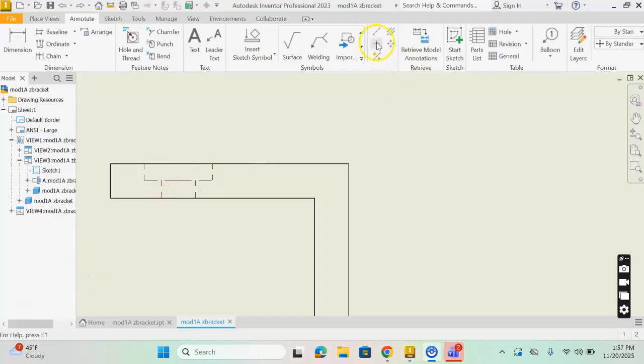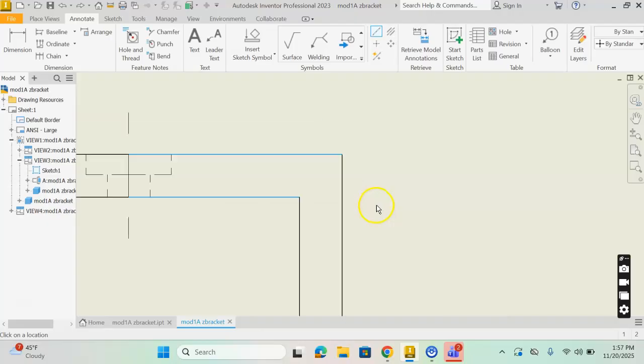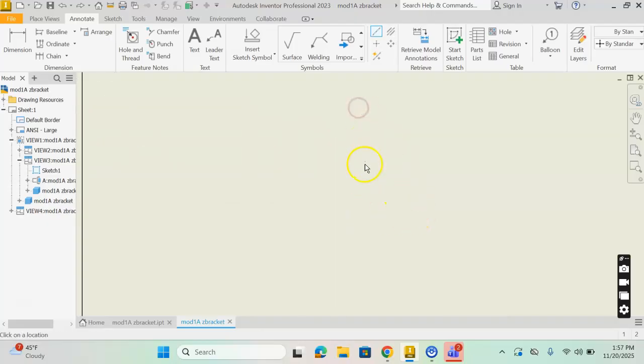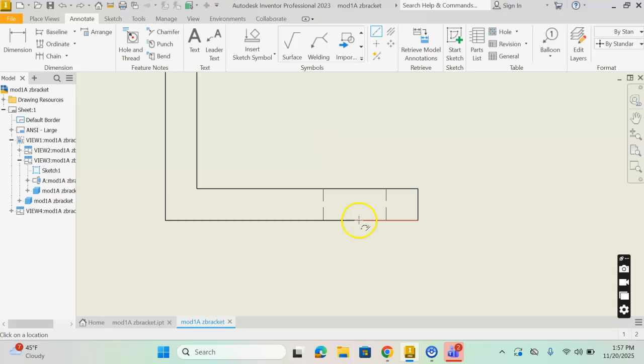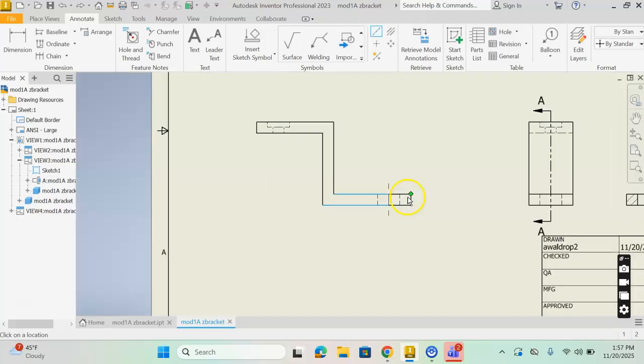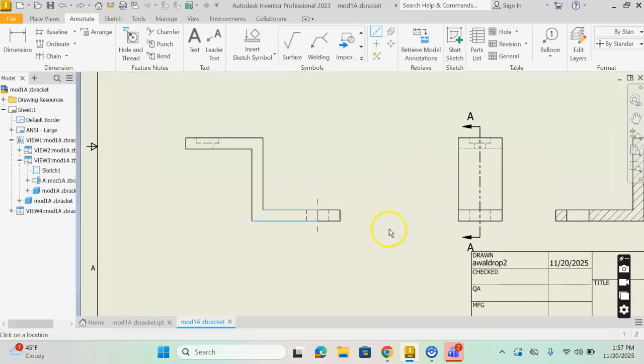So again, I got to click on the axis bar or the icon up here on the menu. Click the two areas that are going to form the center line. And once I click on that, it'll give me the axis center. I zoomed in so that we could see a little bit easier. Okay, and I'll do the same thing down here for my centers. Whoops, that was a mistake. Right here and right there, and it'll automatically put it in there for me.